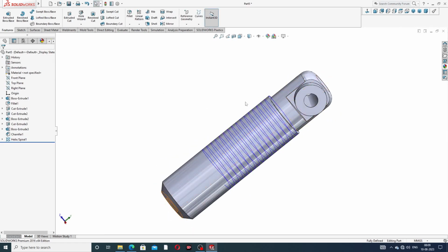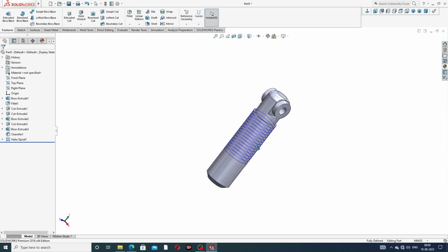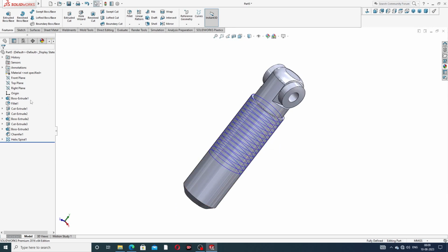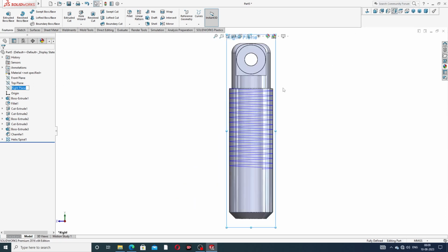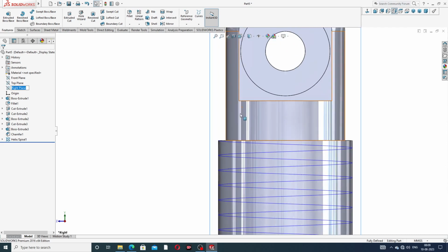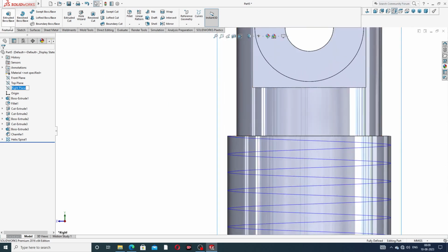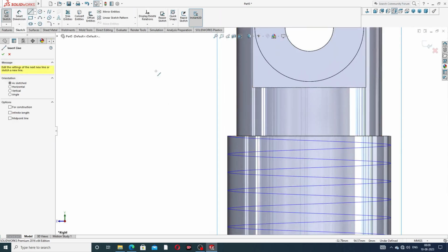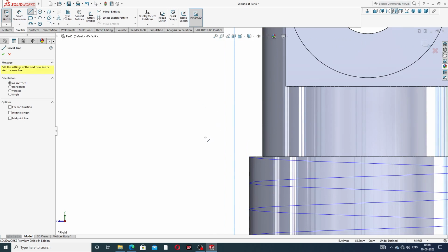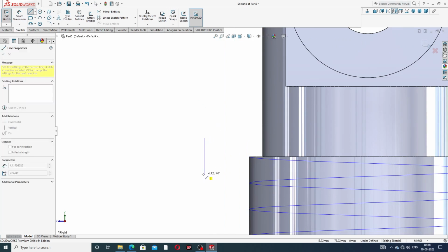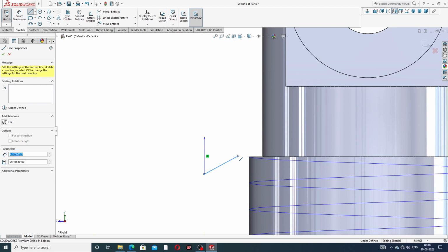Okay, and also select, drawing a rectangle, then this is a cutout, and use the right plane, sketch normal. Okay, this plane is perfect, and align, drawing a rectangle. This rectangle is perfect.